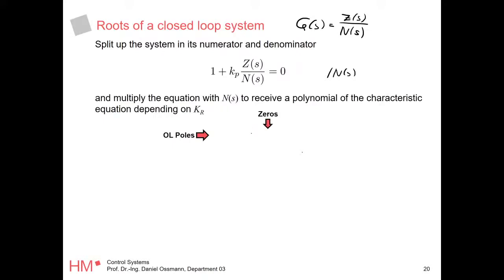This is a pretty simple mathematical computation, but it shortens some calculations you need to do, because your closed loop poles are always going to look like this. You need the zeros of your system multiplied by Kp, and you take your open loop poles, which are on the left hand side. This is why I solve those double fractions so quickly, because I'm always doing that in my head. So I'll give you an example of how this works.